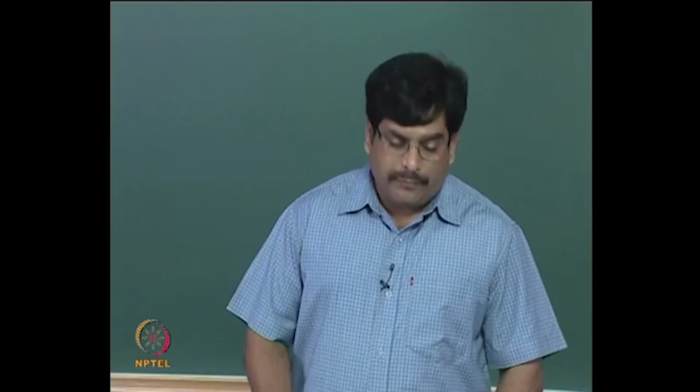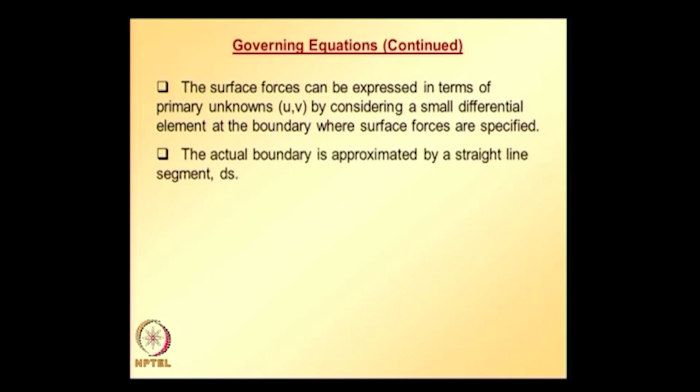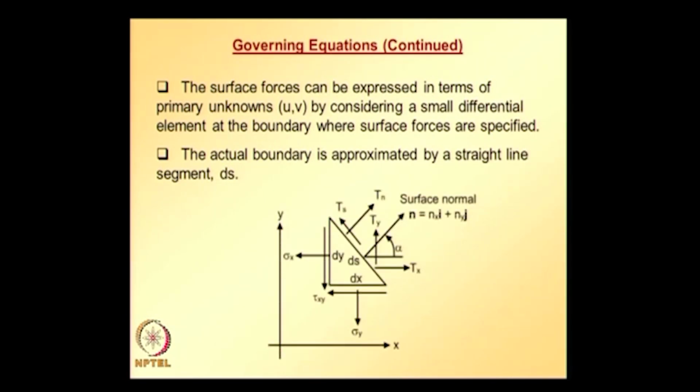So, first we need the relations between tractions and stress components. Surface forces can be expressed in terms of primary unknowns by considering a small differential element at the boundary where surface forces are applied. The actual boundary is approximated by a straight line segment ds, the idealized boundary.